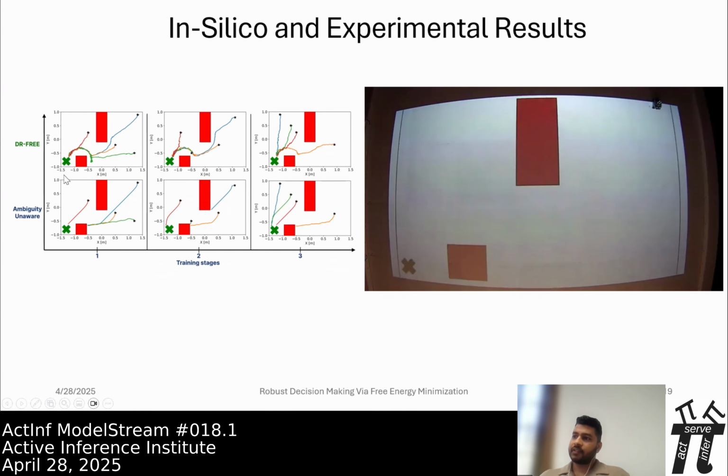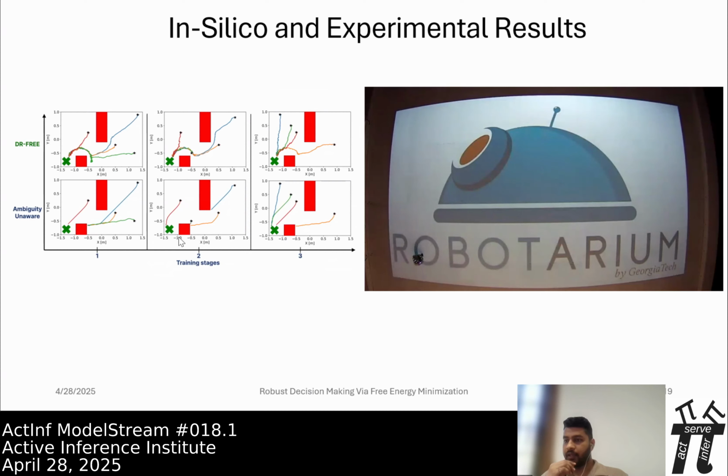Here in this case, the location is provided by the camera. The top camera is tracking the robot, computes the location, and updates the location on the grid. Also, it has the input: it knows the obstacles' locations, because it is given in the cost function. We define the obstacle points, so it knows the obstacles are present. So when it comes near the obstacle, the cost function is automatically very high, and it avoids the obstacle immediately. I hope it answers your question.